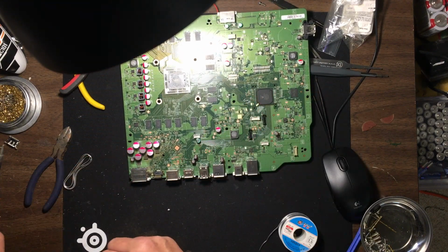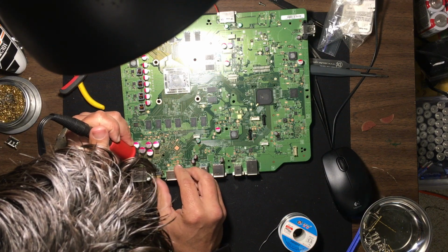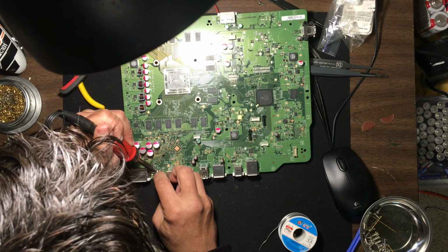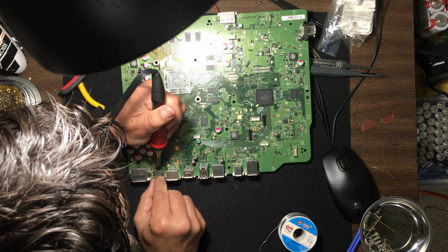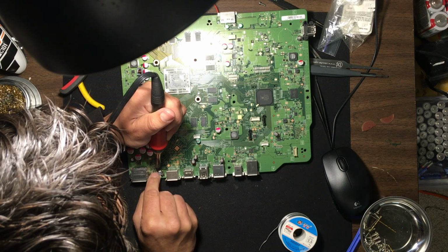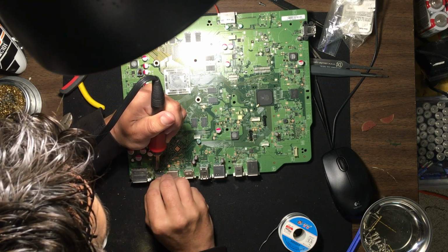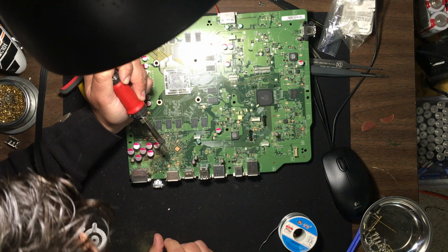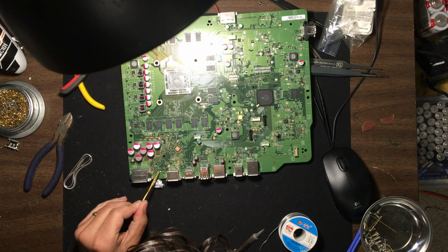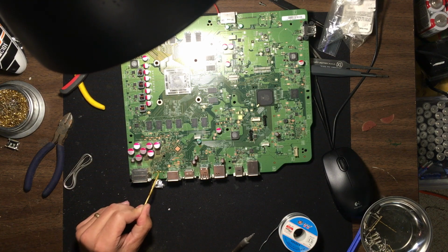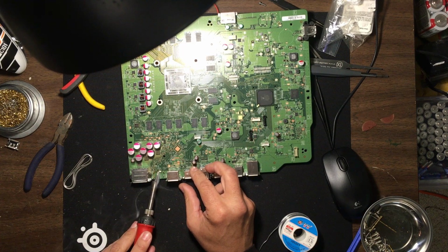I have the soldering iron ready to go here, and let's see if it's enough to get this port off. So you can see that low melt solder there is working its magic. Keep going here. Seems to be walking. Still a little bit of, there we go. Okay. There we go. So that's the port off. Now I've got to clean these things up a little bit. I'm going to put some stuff down. I didn't apply any force there. I kind of pushed backwards with the soldering iron, went back and forth, and just let it naturally fall off.